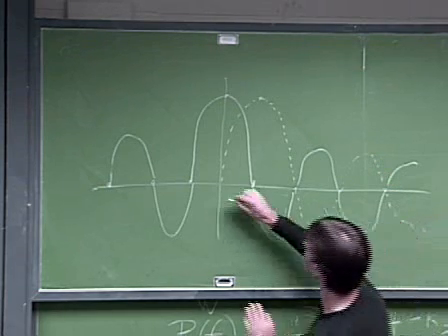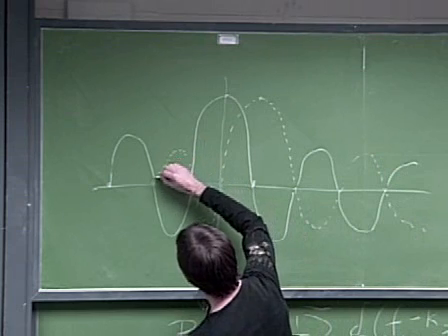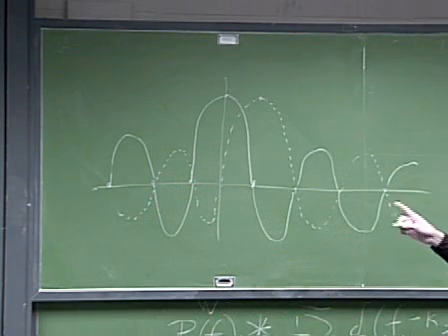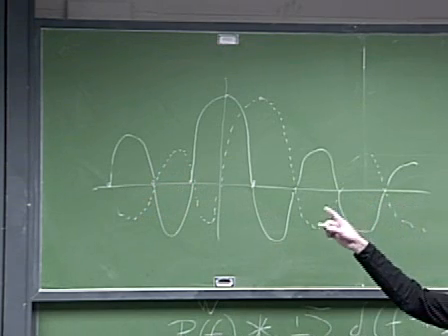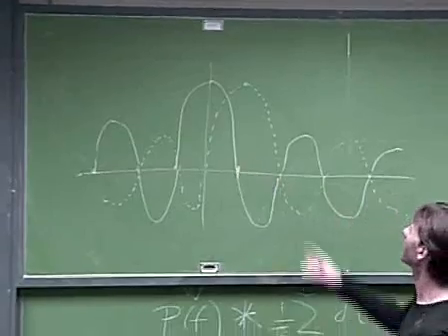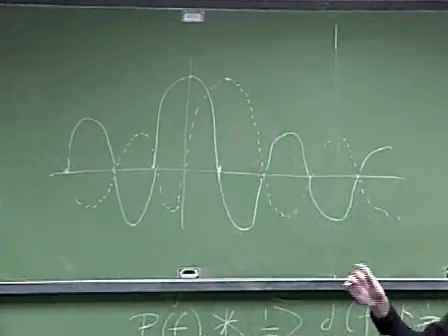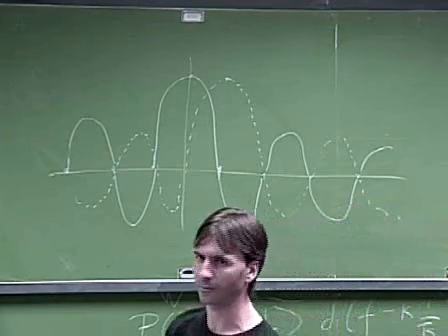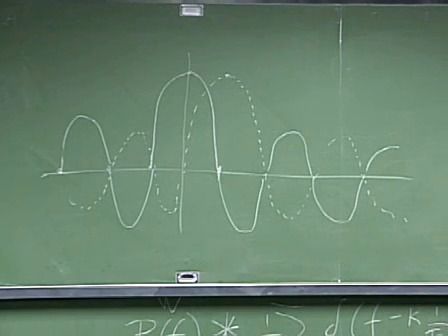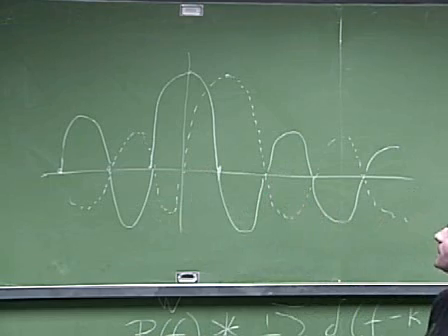Hopefully you get the idea, right? It's supposed to be the exact same shape, but shifted by one symbol time. And it has different information. It could actually be flipped over, depending on the bit, with a different phase or sign. For example, if it's BPSK, it could be 1 or -1. But shape-wise, it's the same shape, just delayed by capital T.